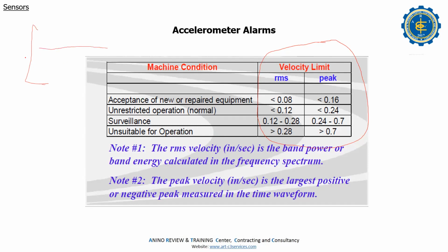Even if you start with 1 mm per second, or maybe 3, we go higher. But your vibration is like this, normal, so there's no problem. Compare if this vibration monitoring is 0.5, but it goes higher, that's the problem.